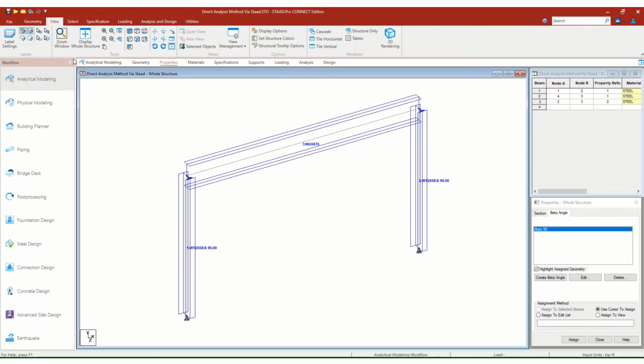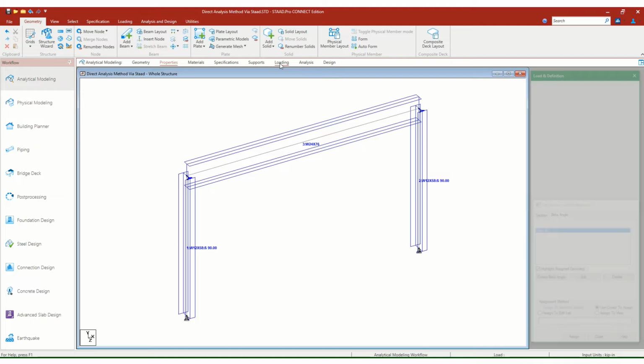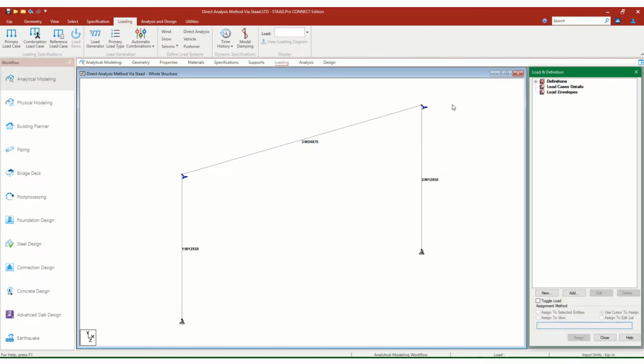And let's go ahead and set our units. I like to go back real quick to inch pound. I'm sorry, inch KSI units, basically inch kips. So hit apply, because when I go into the loading section of the analysis and I set my direct analysis